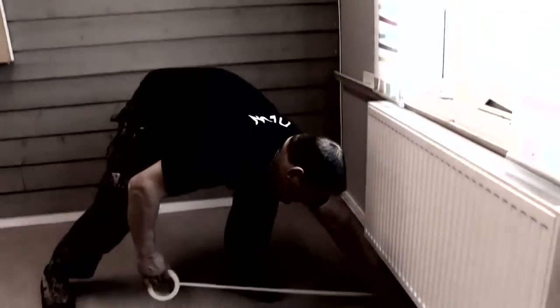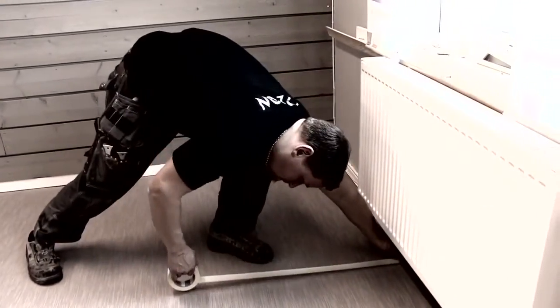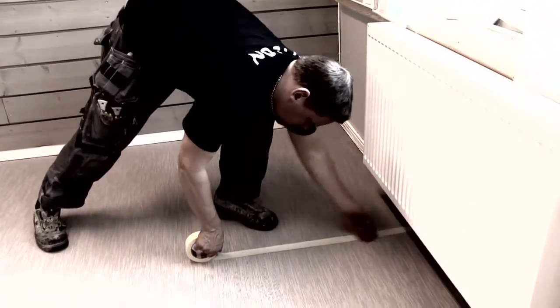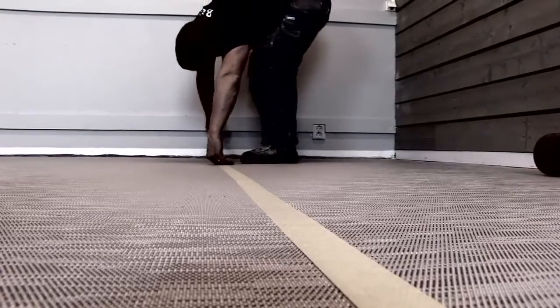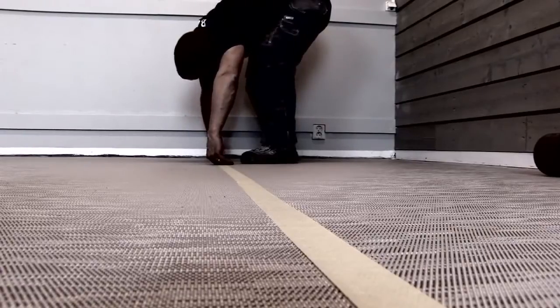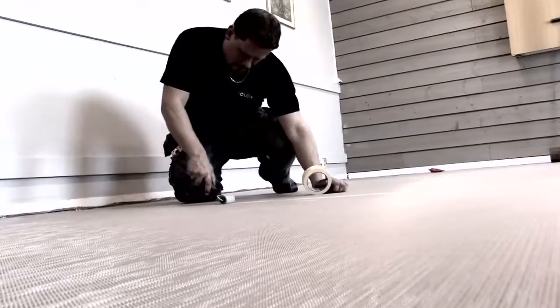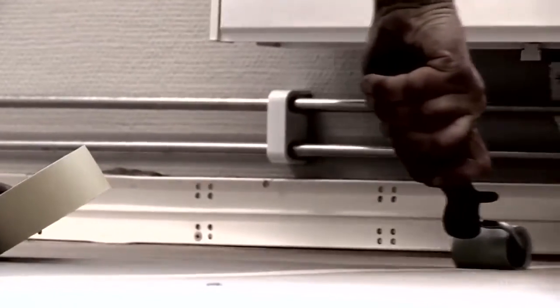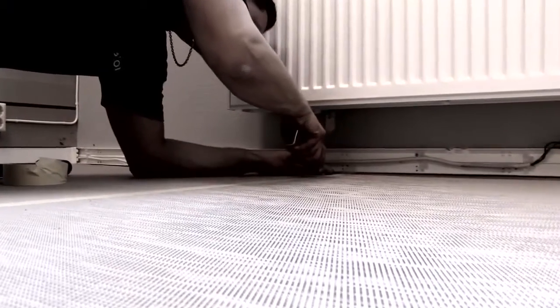For sealed seams, finish the installation by cold welding the seams. For this flooring, use masking tape to prevent overflow of cold weld on the carpet. Ensure that the tape is in contact with the carpet by pressing down using the narrow roller. Cut through the tape using the seam.